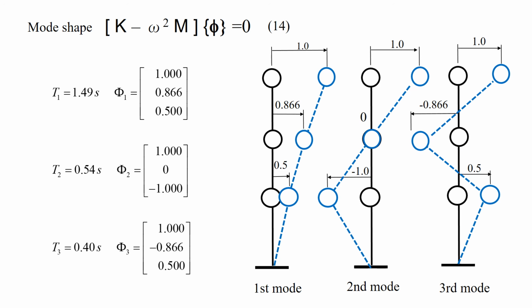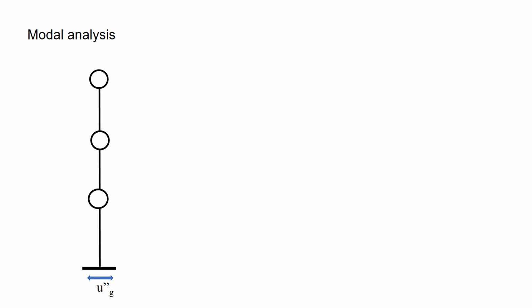Next, we can get mode shapes by equation 14. As you understand, there are 3 modes and the 3 shapes are obtained like this. This shows the concept of modal analysis, where this 3DOF model is subjected to seismic ground acceleration. It vibrates like this.